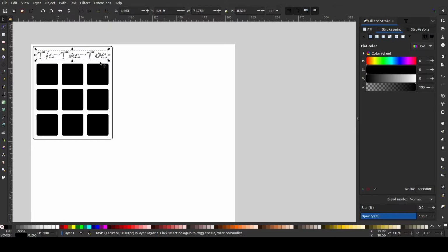So there we are. So now I can tell the Glowforge just to trace the outside, the outline of this font. Now, the thing to remember about the Glowforge is that it doesn't know what to do with text fonts. It doesn't know how to process them. So you have to convert any words that you've typed out in the font lettering into a path. To do that, you come up here to Path and you go Object to Path. And when you do that, you'll no longer be able to edit the text. But this is the crucial step that you need to follow to make sure that the Glowforge will actually score the outline of your font.